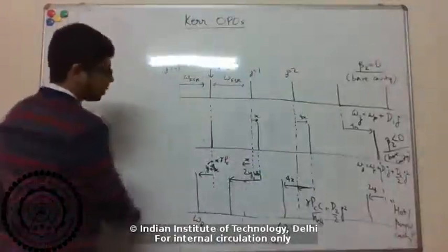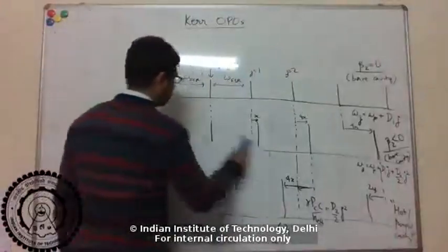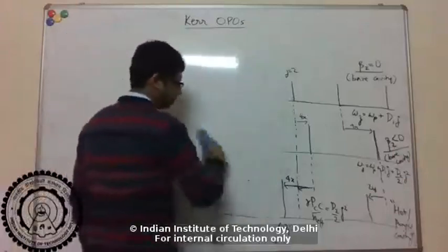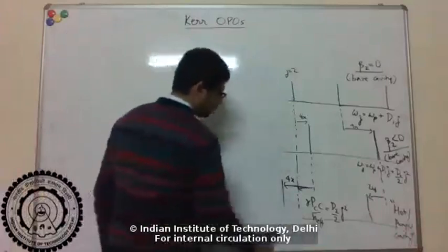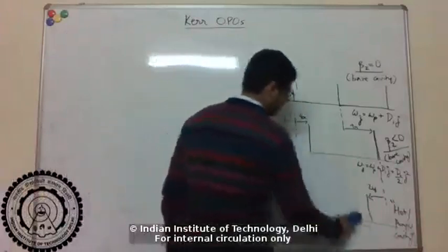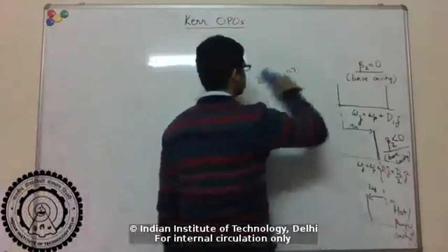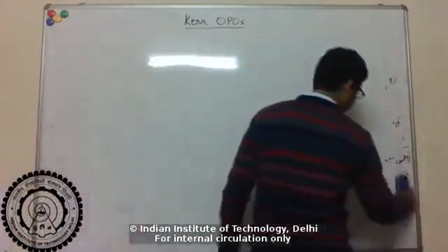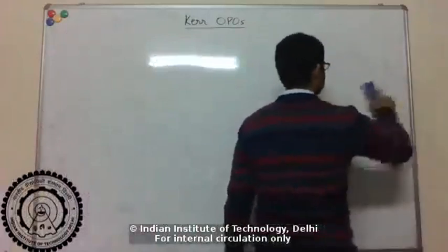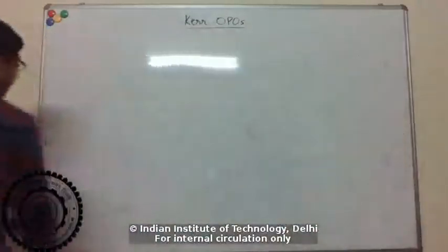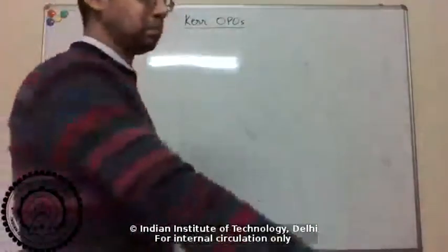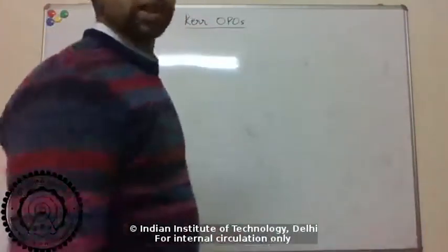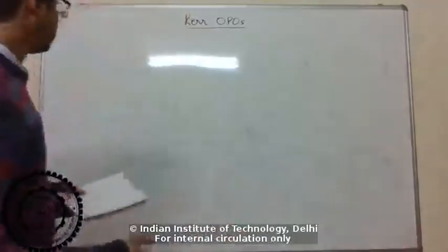But recall, to get the oscillation going, basically we want the gain in the cavity to overcome the loss, right? So something like a laser action, where the gain within the cavity overcomes the loss, only then will you get oscillation or bright light coming out at the signal and idler frequencies, right? So there is some threshold condition. You need a minimum pump power to get some signal or idler out. So we can look at that now.